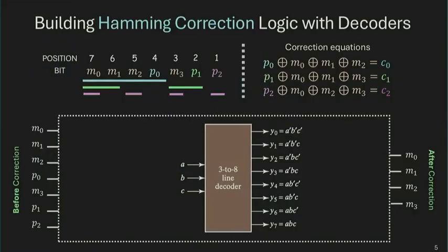All right. And we can use this component to build our error correction circuit, a connection to what we learned in week 1, I suppose. So error correction circuit takes a 7-bit message that the receiver received, and then we're going to do some processing to produce a correct 4-bit message. Right? I have to think for a second. How do you think we can implement this logic? Right? The goal is really to, for one thing, calculate those correction equations, and then use the correction code to find out one index to make the correction. So think a little bit how you would implement that circuit using decoder.